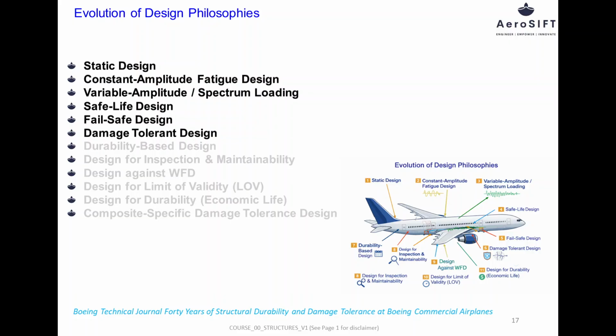Durability-based design focuses on preventing fatigue damage from occurring during the early and economically important portion of an aircraft's service life. The goal is to minimize crack initiation for a specified number of years or flight cycles, thereby reducing maintenance burden and repair costs. This approach improves long-term reliability and ensures that aircraft remain economically viable while operating safely.